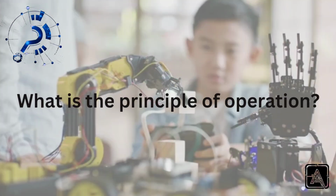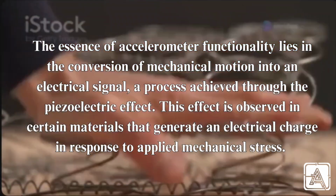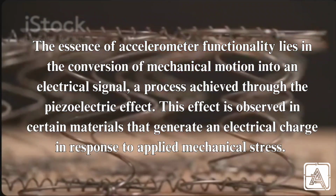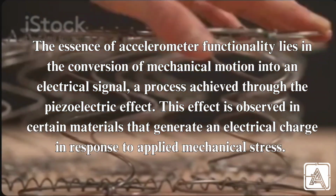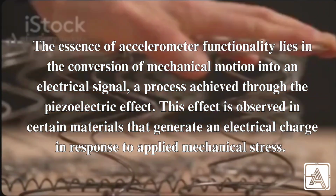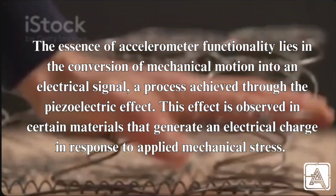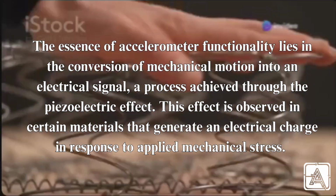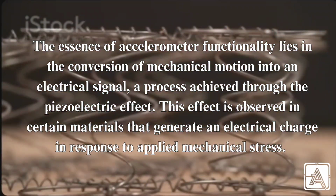Let us see what is the principle of operation of an accelerometer. The essence of accelerometer functionality lies in the conversion of mechanical motion into an electrical signal, a process achieved through the piezoelectric effect. This effect is observed in certain materials that generate an electrical charge in response to applied mechanical stress.